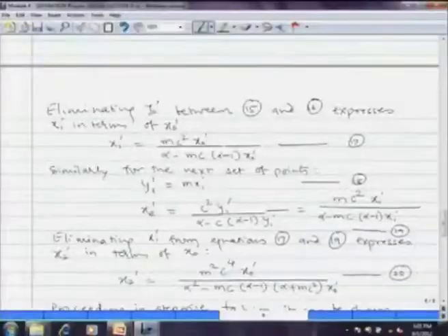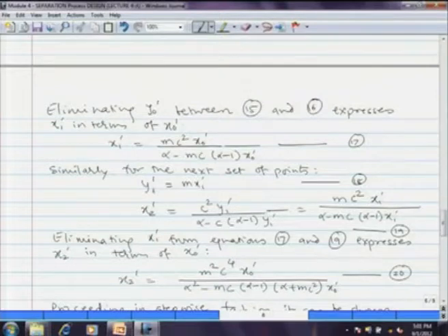That is why we have made all our calculation explicit in terms of x and not y. Determination of composition of vapor requires special techniques such as gas chromatograph or liquid chromatograph, basically gas chromatograph, and that is more tedious, but measurement of the composition of liquid is much easier.